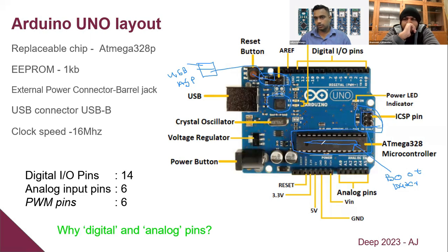Without the bootloader, you can't program this through USB. Let's say you buy one of these blank chips from Amazon or eBay. It does not contain a bootloader, so you have to use a separate programmer first to bootload this IC. Then you can use that IC in this board, plug into the computer, and program it. Is that clear, Ajit?